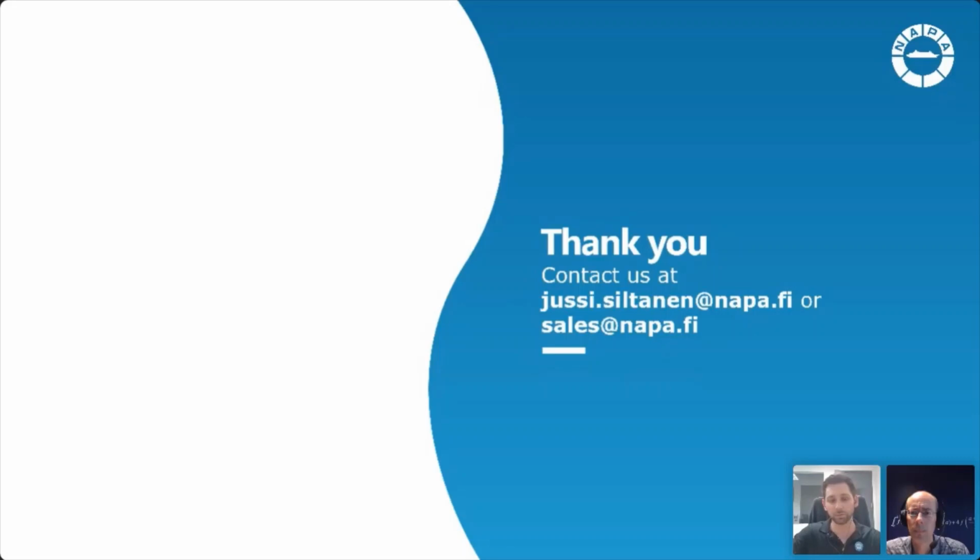But for the tank levels, if for example there's an issue with the tank level sensor, you can actually override the level being used in the NAPA Emergency Computer by entering it manually in the NAPA loading computer with the option of sensor broken for the status of that particular tank. If you would like more details on how to set the tank levels manually, I'd be happy to send you that in an email afterward.